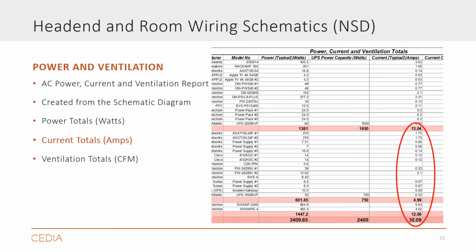What about the total current requirement for both our racks? Here we see 3 power connection group subtotals. Why 3? We only have 2 racks, so what gives? Well, the third power group has to do with the 2 audio power amplifiers, which typically draw more than PDUs and UPSs can handle. So they are both directly connected to a third surge protection circuit.